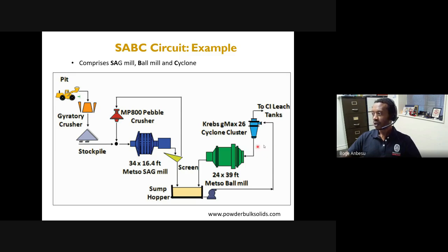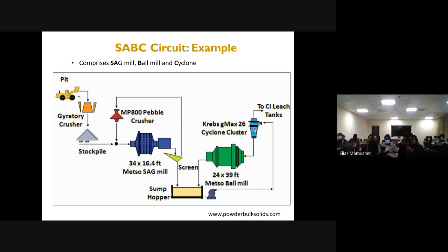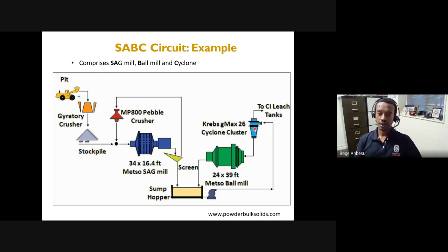And of course, the ball mill is operated in closed circuit with, for example, a cyclone. So hydrocyclones are typically used. Again, the main purpose there is to split the particles into fine and coarse. The coarse particles are sent back to the mill and crushed and ground, in this case with a ball mill. The fine particles can be sent to flotation, gravity separation, whatever the case may be. So again, in this case, the cyclone is used to control particle sizes going into the next processing step.